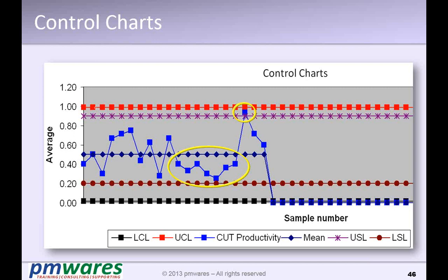Okay, so every time we produce something, we put up a point on the control chart and see whether our graph is good. The graph is good when we get these points randomly; the randomness is the key for a control chart. Anytime we see that this chart is not appearing random, or randomness is lost, it is indicating a problem. We need to investigate it.